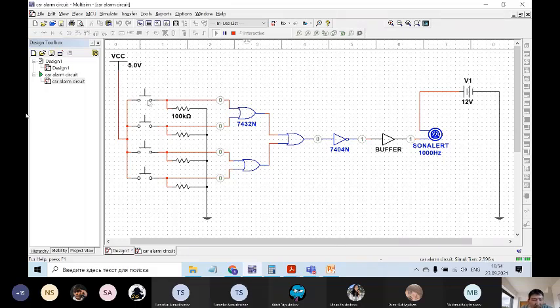Okay, when I push, just watch this reading. It is a probe. For example, I put here 1, right? Up till now it is an OR gate. When I put here we also have 1, but after it will be inverted. Now you can see it's 1. When I push, here you can see 0.